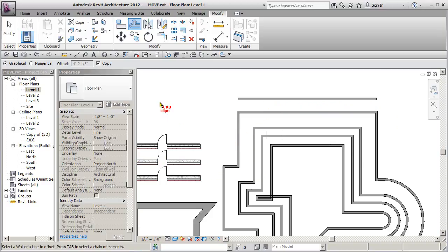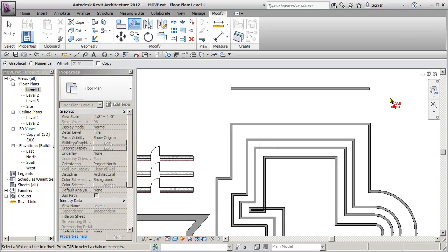I can't say I even remember the last time I used that, because I would rather just copy it, but I'm sure there's a reason for it. Mainly I use this. So graphical, you pick the points when you do the offset. If you take the copy off and then you do the offset, it erases the original, which is basically just a move. But offset is going to be parallel rather than a move, which would go in any direction you want.